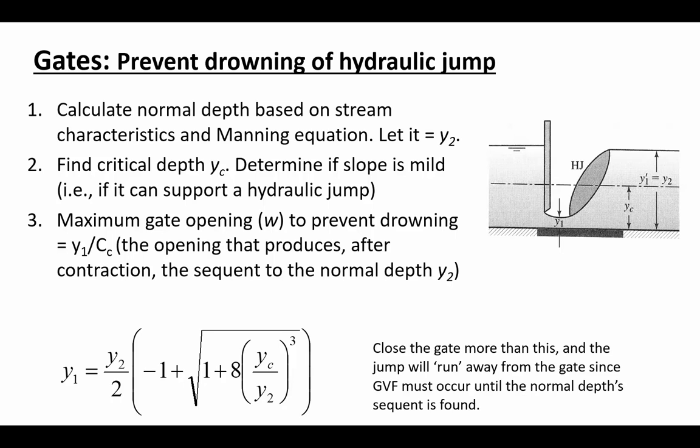And the textbook gives you both forms of that equation, but this is solving for the upstream depth rather than the downstream depth, because in a question like this, like how much can the gate be opened, the starting point, the known, is not the upstream depth. The known is the downstream depth that you would get from Manning's equation.